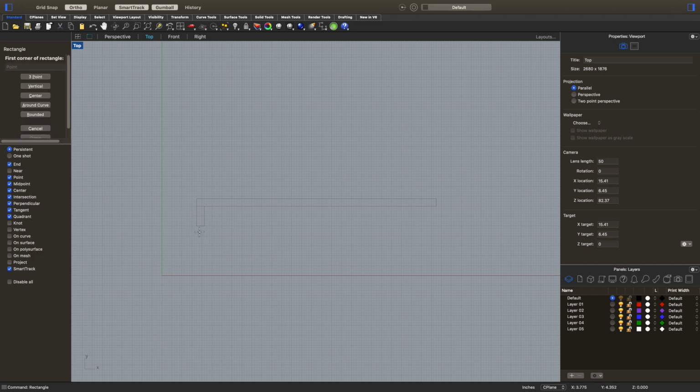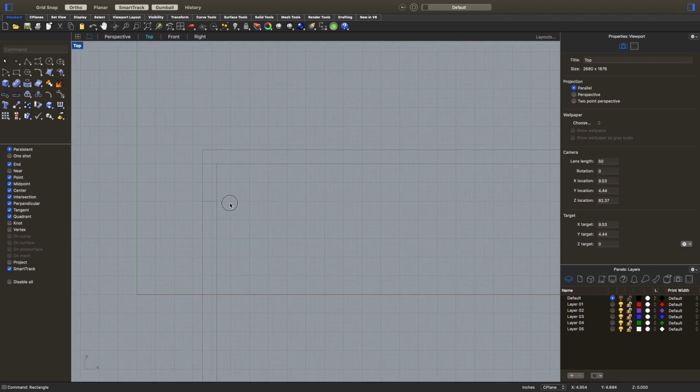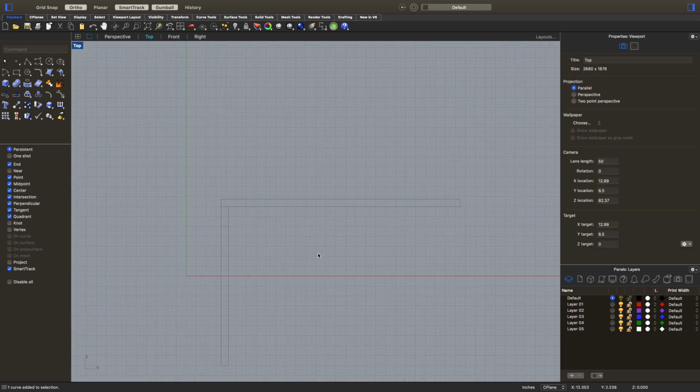Then I'm going to draw another rectangle from here. I'm using my snaps, rectangle, snap to there, and I start to draw out. Left to right is 3/4 of an inch, enter, and then 14 inches, -14, sorry, to go that way. That's going to be for our side piece.